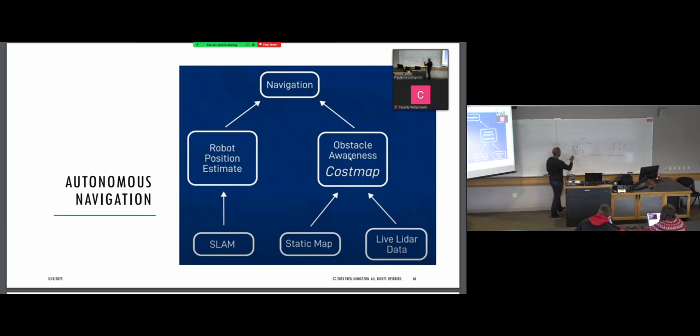And these scenarios are going to have a penalty, what we call a cost map. So when we're doing obstacle avoidance, we get a penalty if we go into this area, and so it's going to try to avoid that area. There's no penalty here; the penalty is 0. Let's just say it was 8-bit, 255 here, and it's going to try to go through a path with the least resistance, just like current, and compute its own trajectory path. That's where we can build a cost map. So each one of these cells is going to have a cost associated with it, and it's going to compute a path using the least cost to that destination.